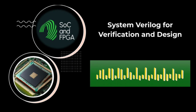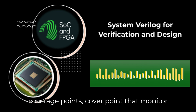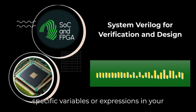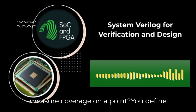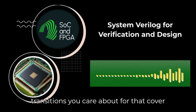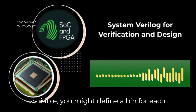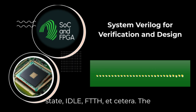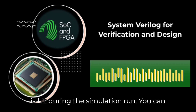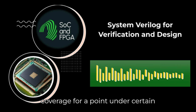You create a covergroup, typically within a class or interface. Inside the covergroup, you define coverage points, coverpoint, that monitor specific variables or expressions in your design or testbench. And how do you measure coverage on a point? You define bins. Bins specify the values or transitions you care about for that coverpoint. For example, for a state machine variable, you might define a bin for each state, IDLE, FETCH, etc. The simulator tracks how many times each bin is hit during the simulation run. You can also use iff to conditionally disable coverage for a point under certain conditions.